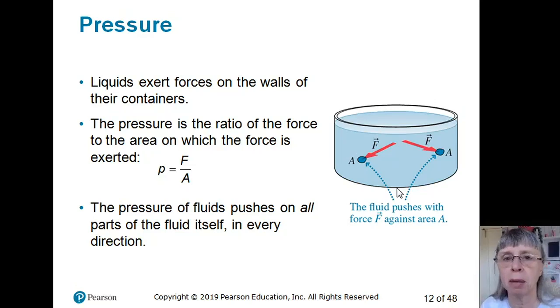So clearly the bottom of the container is applying a force to the liquid. And it's not so obvious that there's pressure on the sidewalls, but there is. The easiest way to think about that is if I were to put a hole in the side of this, the liquid would be flowing out. So the container is applying a pressure to keep the fluid inside. So of course we know from Newton's third law that every force has an equal and opposite reaction force. That means the fluid is also applying a pressure on the side of the container.